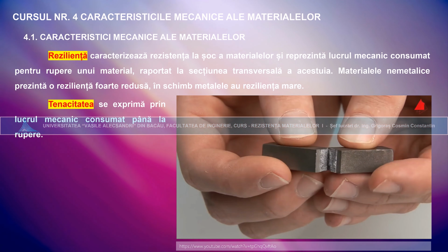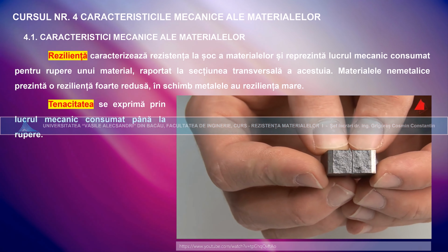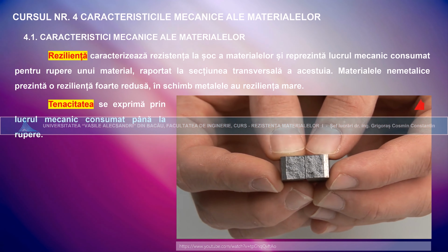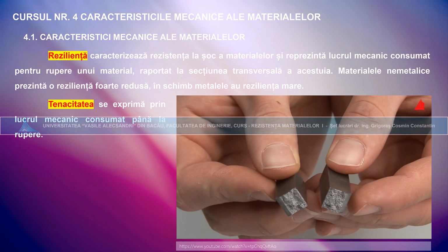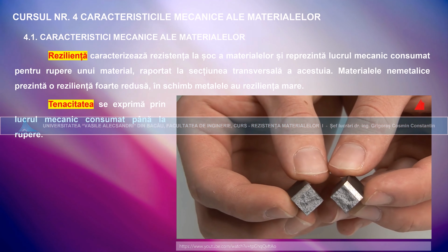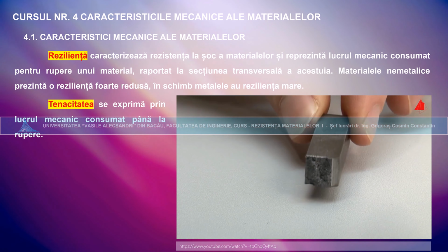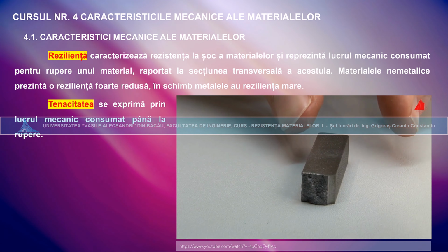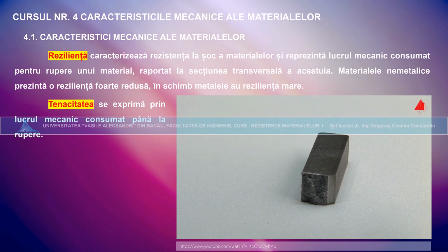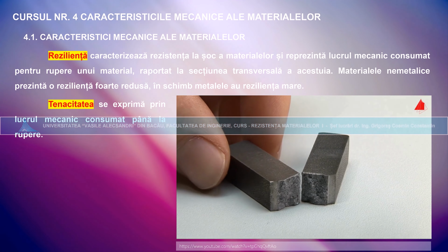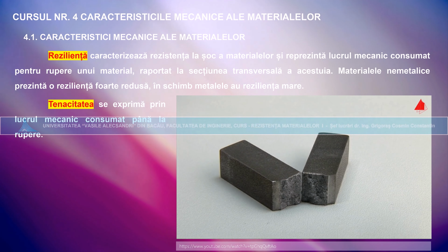The first specimen only shows very little plastic deformation. A mostly flat, slightly glittering fracture surface has been formed. This is another important indication that this kind of steel is only able to absorb small amounts of notch impact energy. It shows mainly brittle behaviour due to the strain aging effect.